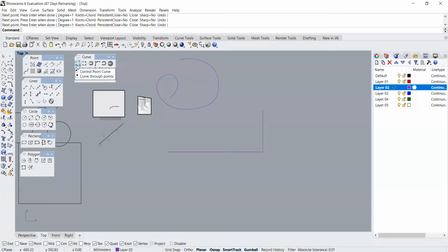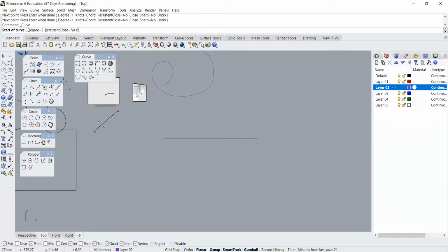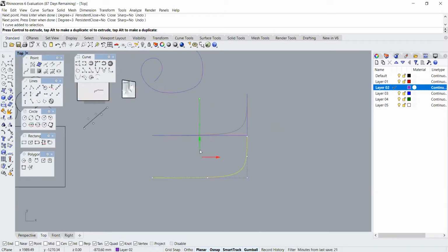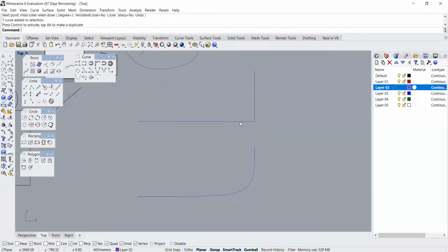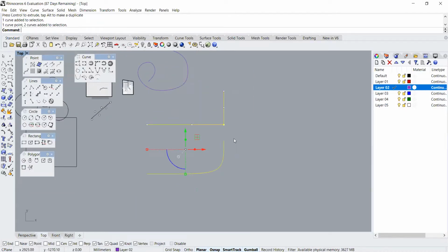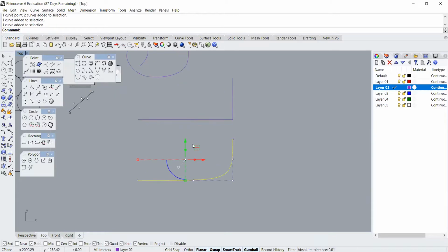I've used the same command here, which says control point curve. I'll use the same thing once again. Now the degree is 3, and when I'm using the same line, see, now because of the degree, the curve over here has taken a deviation. It's taking a curved shape, whereas both of these are from the same command. But because over here we have degree 1 and here we have degree 3, that's why it's different. A minimum of degree 2 can give us a deflection in the curve.